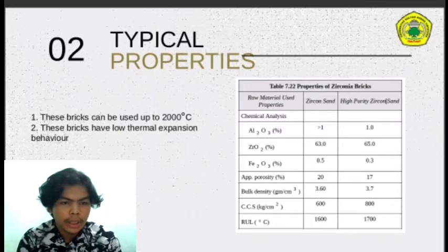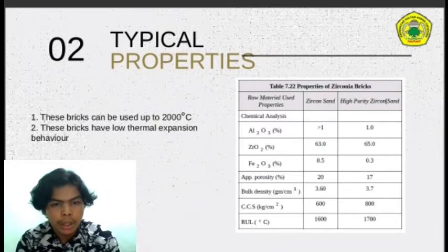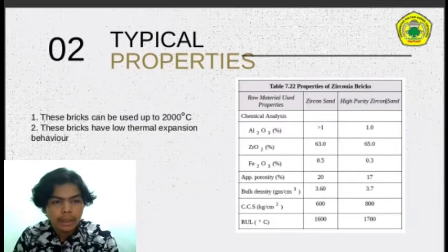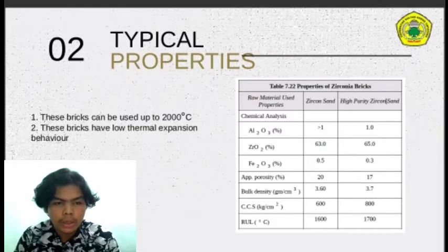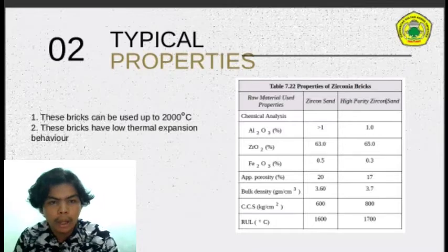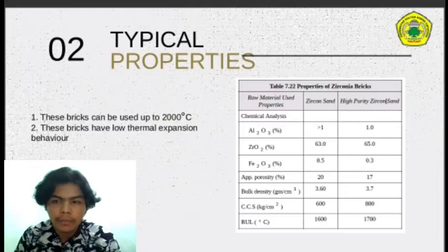Next, CCS, zircon 600, high purity zircon 800. Next, refractoriness under load, zircon 1600, high purity zircon 1700.